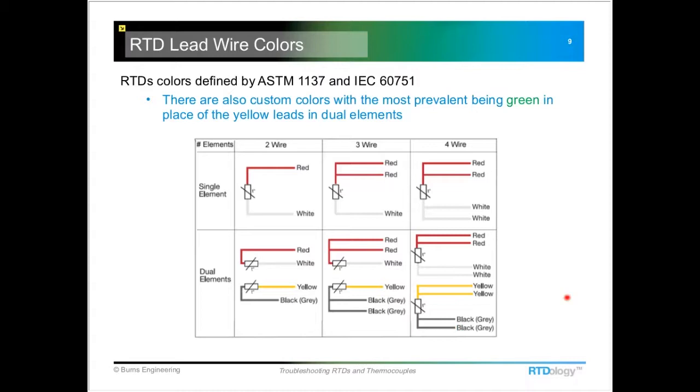We use the red and white. It's just a historical thing with us, and I think Rosemount uses that same coding, and I've seen several others that do the same thing. So you may see a little variation there. But the circuit is really fairly simple. We've got the sensing element here with the two red leads connected to one side of it and the whites connected to the other side. And these are for lead wire compensation.